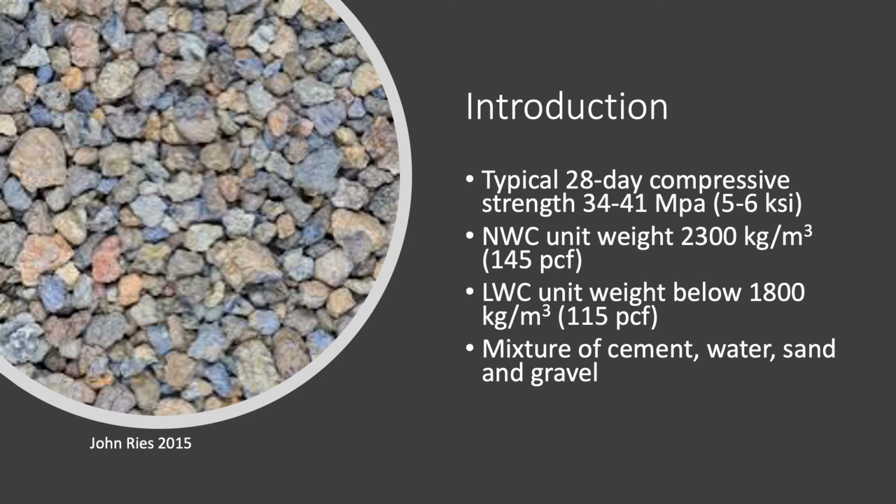The primary use of structural lightweight concrete is to reduce the dead load of a concrete structure, which then allows the structural designer to reduce the size of columns, footings, and other load-bearing elements. Structural lightweight concrete mixtures can be designed to achieve similar strength as normal weight concrete. The same is true for the mechanical and durability performance requirements.